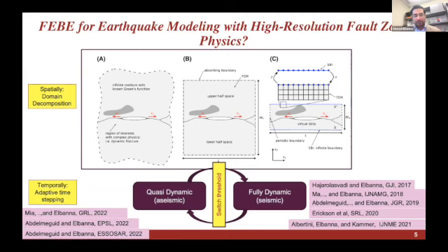any of your favorite volumetric or domain-based approaches. But then we cannot forget about the exterior half spaces, because this is our loading machine where waves will propagate and strain energy is stored. So what we do is we replace the exterior half spaces by an effective boundary integral description. On the boundaries of this virtual strip, we have a boundary integral formulation that relates the traction to the displacements and velocities on that virtual strip. And the way we couple these two is by enforcing continuity of traction and displacement across the interface.